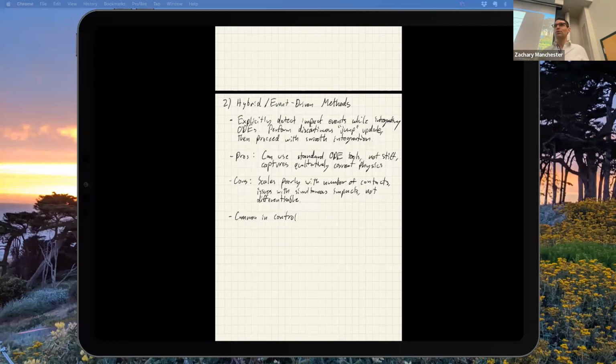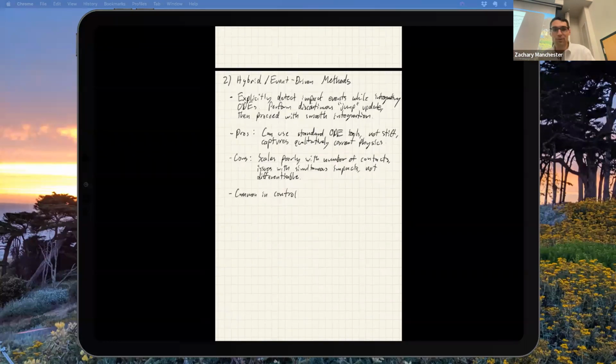But in general, if it's a complicated thing with complex geometry and multiple contacts, it gets really nasty. This is called combinatorial mode explosion in the lingo. You call all these different contact configurations modes, and the number of those modes blows up combinatorially with the number of contact points you can have. If you have a continuous surface where you could have contacts anywhere, forget it. You have to explicitly model it as points and discretize it somehow, and then it just blows up. It's really bad.